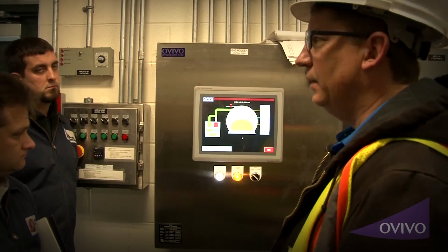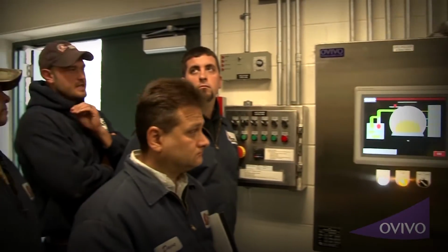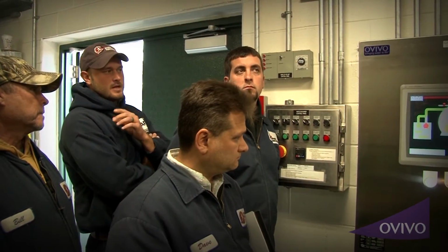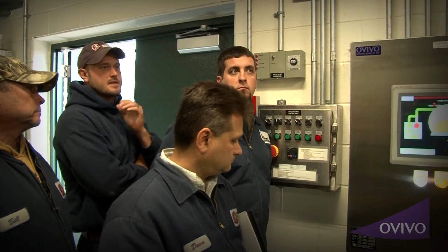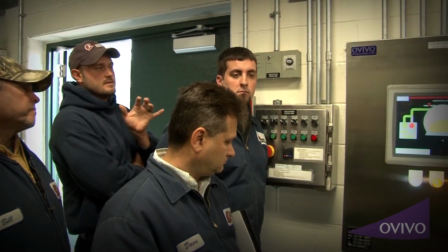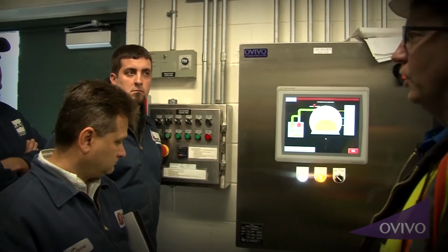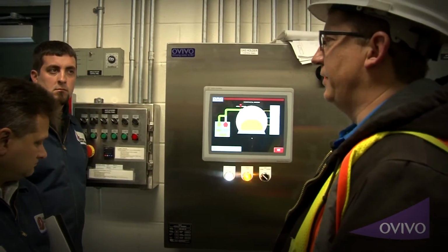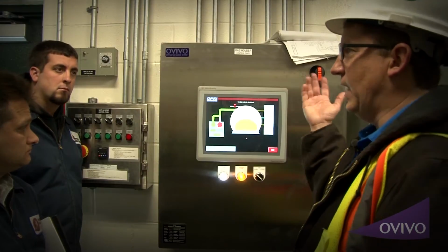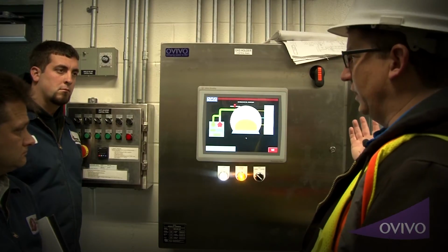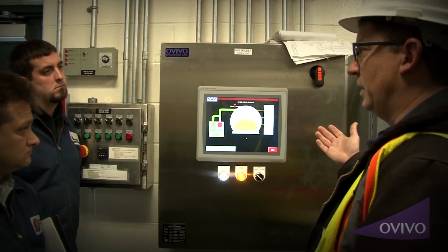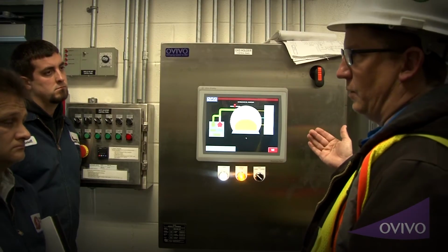Now, I know you said on the LEL between the two, it should never go high because it's purging out constant fresh air. But let's say bad sensor or something, and it does, and it's showing you have an LEL. What's the programming going to do itself? It's just going to give you an alarm. I got a high methane alarm, and it can be anywhere from, let's say bad sensor, 0 to whatever. Exactly, and it's not going to actually do anything. It's just going to say, hey, listen, I have a high methane detection. We need to figure out what we're going to do about it from that point on.